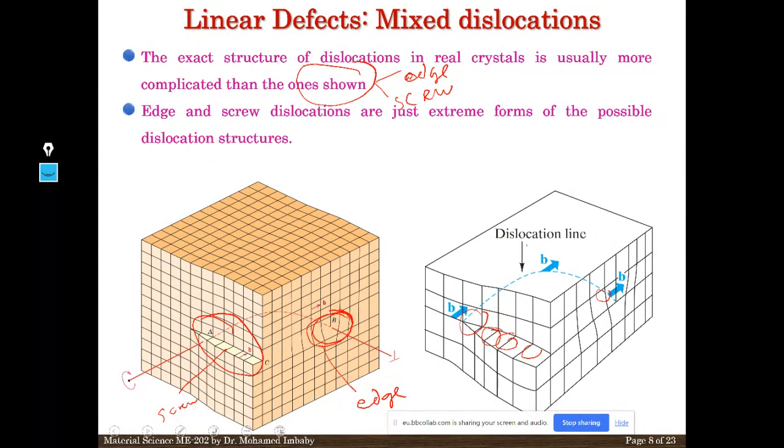As we know, the line of dislocation is perpendicular to the Burgers vector in edge dislocation and parallel in screw dislocation. Second, the Burgers vector has a length, right? If there is a mix, a link between the edge and the screw, they have the same Burgers vector. This is the conclusion I need the students to understand.